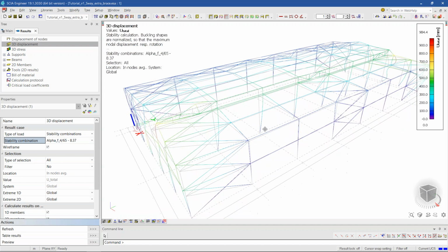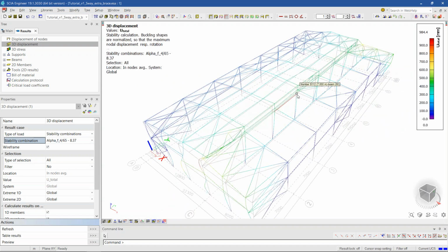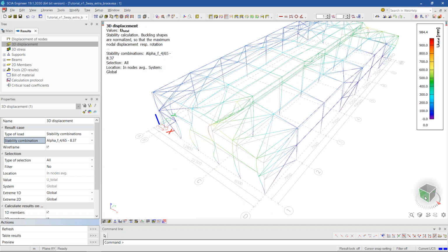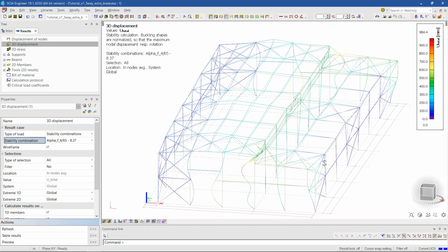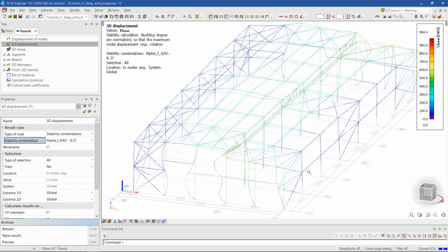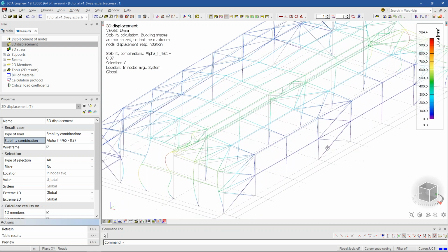It means that certain elements, these columns here, in the weak direction, so the facade columns in their weak direction, are displacing. They sway. This is a sway frame, and you need to use buckling lengths that are bigger than 1.